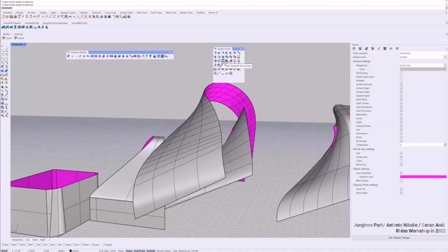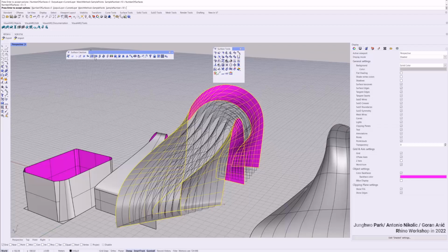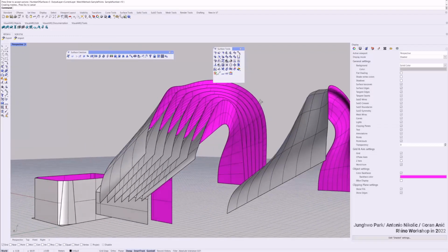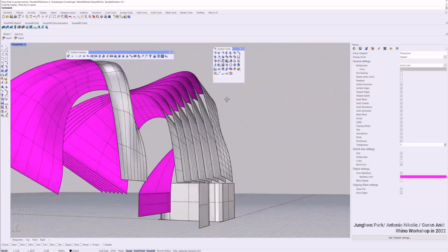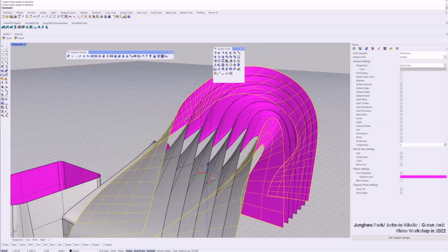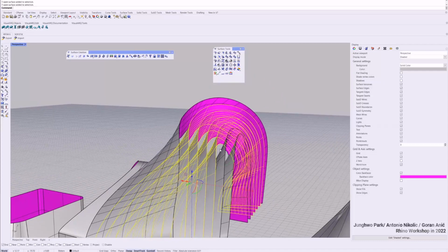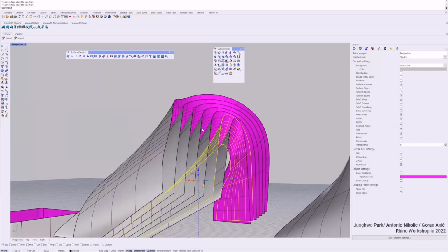And when you do twin between two surfaces, I'll select first surface and second surface, and then I'm gonna give sample number, so number of surfaces I want to create, 3 or maybe 5, and then you can choose different settings. And when you finish it, as you can see, it's not the exact offset surface, but it's twin surface in between first and second. Okay.